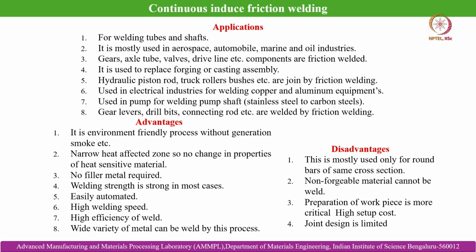There is no change in properties of heat sensitive material, no filler metal is required, and welding strength is strong in most cases, because we are plastically deforming the material at the adjoining region. So you can very well understand that the weld joint will be stronger than the joint we generally produce by the fusion welding route.